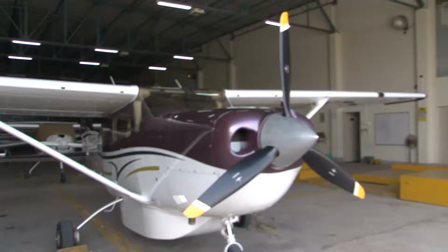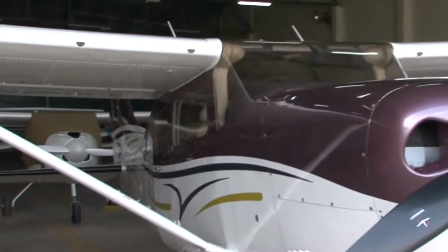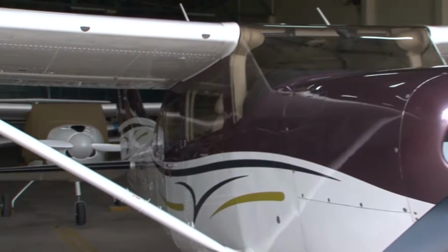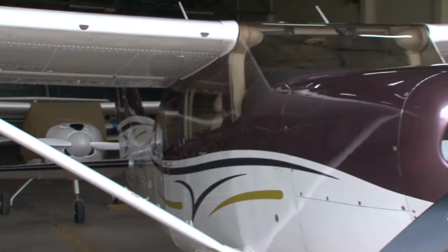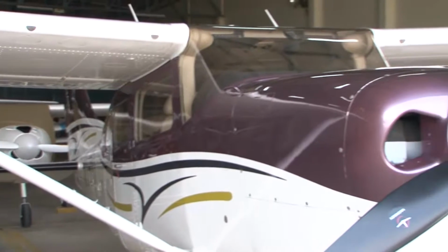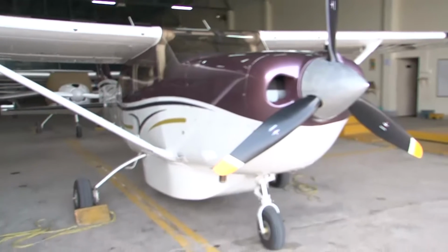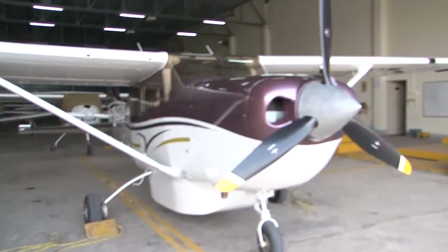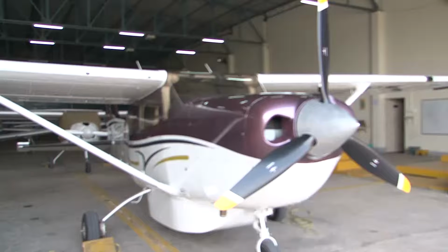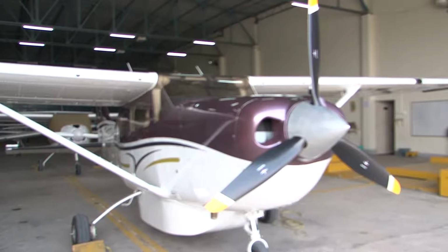You very well understand that depends upon what sort of a number of passengers you are going to carry. But for a 6-seater airplane, the width is around 50 inches, which is around 4 feet, and the height is around 43 inches, which is around 3-point-some feet. So 50 inch and 43 inch is the cross-section width and height of the fuselage.